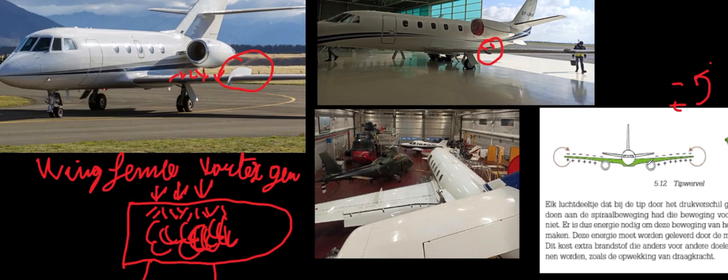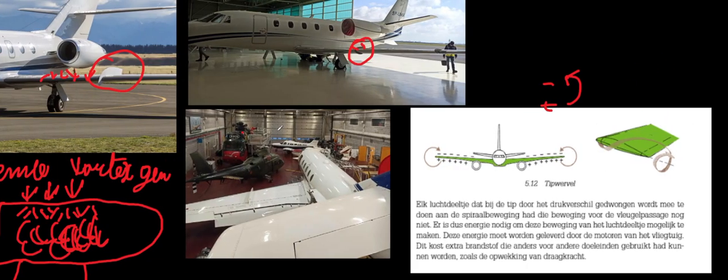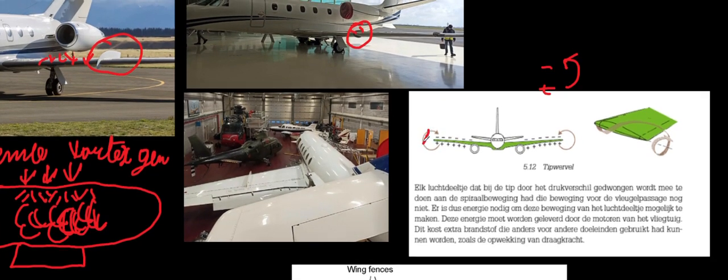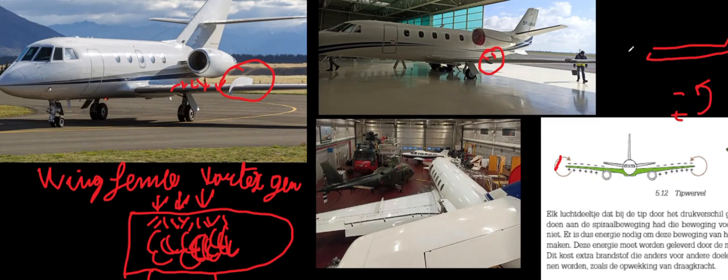I think when the Falcon 20 was made, the engineers didn't think that much about it because it wasn't that much of a worry back then. But now we want our aircraft to be as efficient as possible. So what is one of the solutions to that? It's a winglet, like this one. It's actually a little wing we place at the end of the bigger wing, and the little wing actually has the same problem, but because it's a little wing, it causes way less induced drag. And our big problem here is solved and turned into a way smaller problem. It can actually save 5% to 10% if it's done very well, and that's a lot of fuel and a lot of money. So it's important on new aircraft.